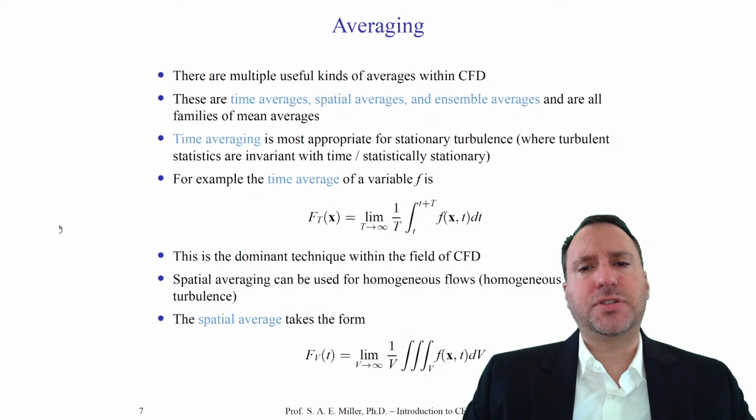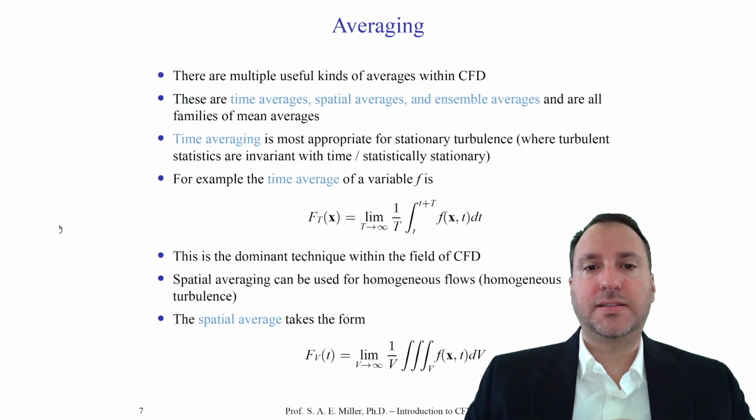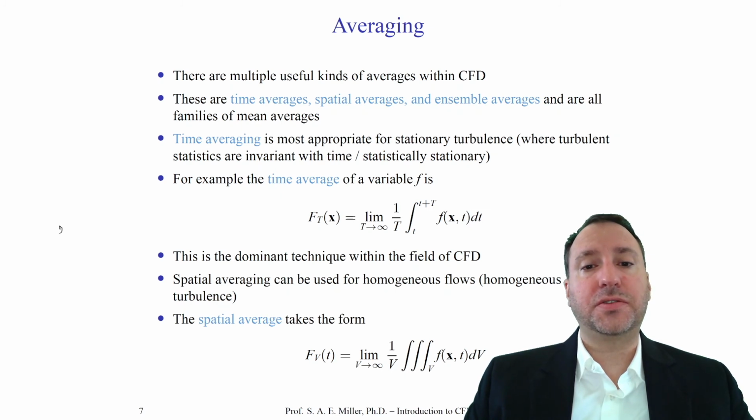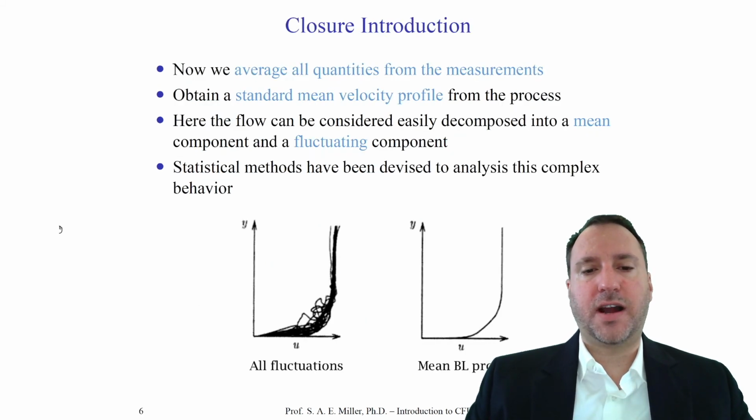But we're more interested in, of course, the turbulent case. So we're not really going to consider these techniques for the steady laminar flow. A steady turbulent flow, remember, is an unsteady flow. That's because the fluctuations are actually moving, velocities and pressures and temperatures and other variables. So when we find a steady solution of a turbulent flow, we're also finding the turbulent statistics, which represent the statistics of the fluctuations, like we showed in this previous graph.